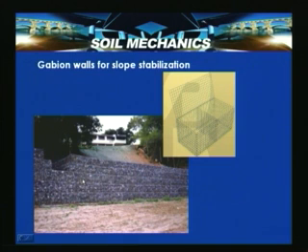The advantage and merit of this gabion wall is that, being a freely draining material, water can seep through it, and because of the gravity or self weight, it also ensures stability. And because of these iron cages, you can have a steepness as close to 90 degrees. So, gabion wall applications are even gaining momentum in India.